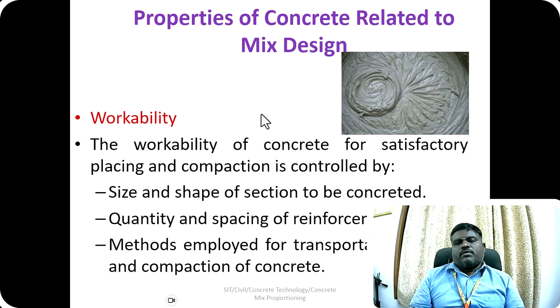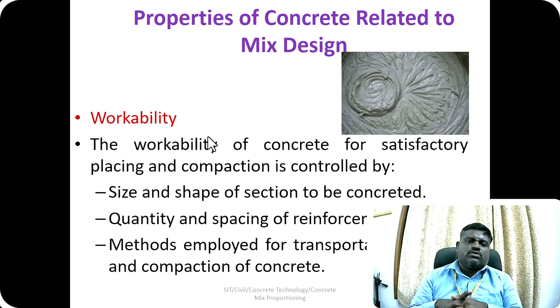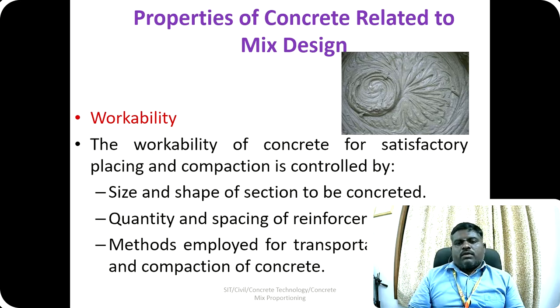The other property is workability. The workability of the concrete is also mainly influenced by the water cement ratio. Here, the workability of the concrete for satisfactory placing and compaction is controlled by the size and shape of the section, the quantity and spacing of reinforcement, and the methods employed for transportation, placing, and compaction of concrete.